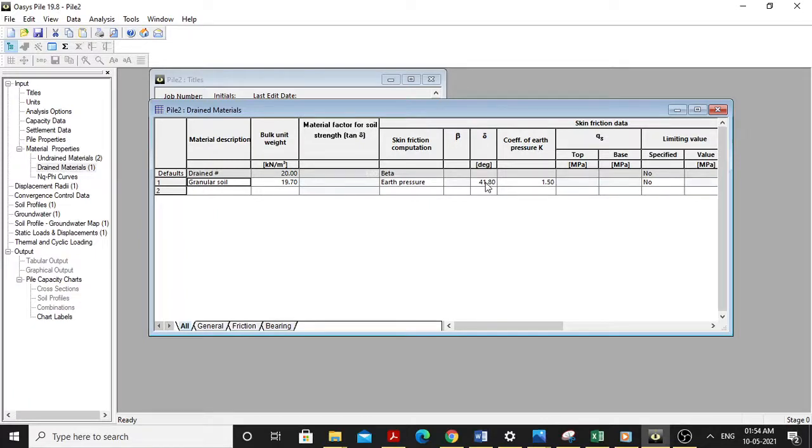and the delta is the same as the internal friction angle. If you check our parameter in the geotech report, we have an SPT N value of 27.7, and it has been derived from this. It was given that if the SPT N corrected value is 22, then the internal friction used to come around 35. So if we are having 27, then in a more conservative way we have given the phi as 41, and we have also compared it with different correlation data from the density as well as the Young's modulus that is given in the report, and found that this is more appropriate to take.